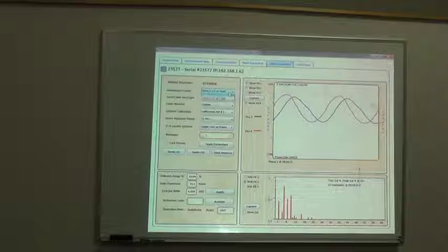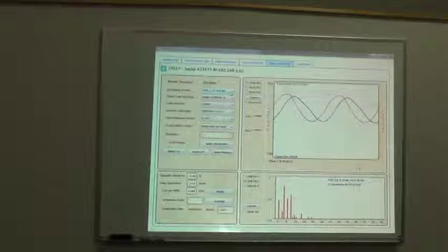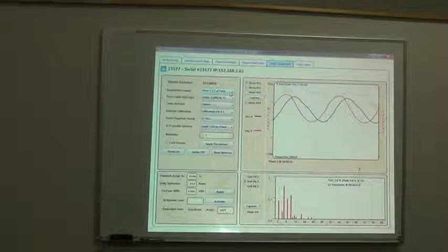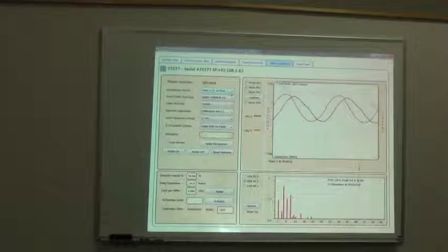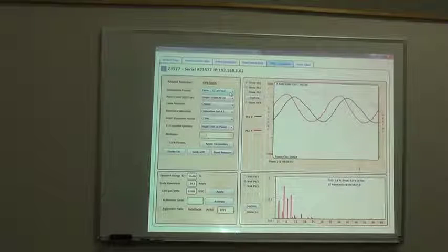The number one is where the CT is. You have to tell us whether the CT is before or after the panel. I was describing one condition to Philip today. If you have one load on the panel that is 40–50% of your entire panel, you really should put the CTs on that load, because you're making the job of the SP1000 much harder. If that load turns on and off too often, the SP1000 will never be able to do a good job.